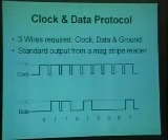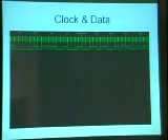Mag stripes basically use a protocol called clock and data, which is pretty simple. You've got your clock pulses along the top, your data pulses along the bottom. The presence of a 1 or a 0 with a clock pulse indicates your data stream. This is actually a bit of my Visa card, but only a small bit, I hasten to add. No significant digits there, but you can clearly see your clock along the top and your data bits along the bottom.